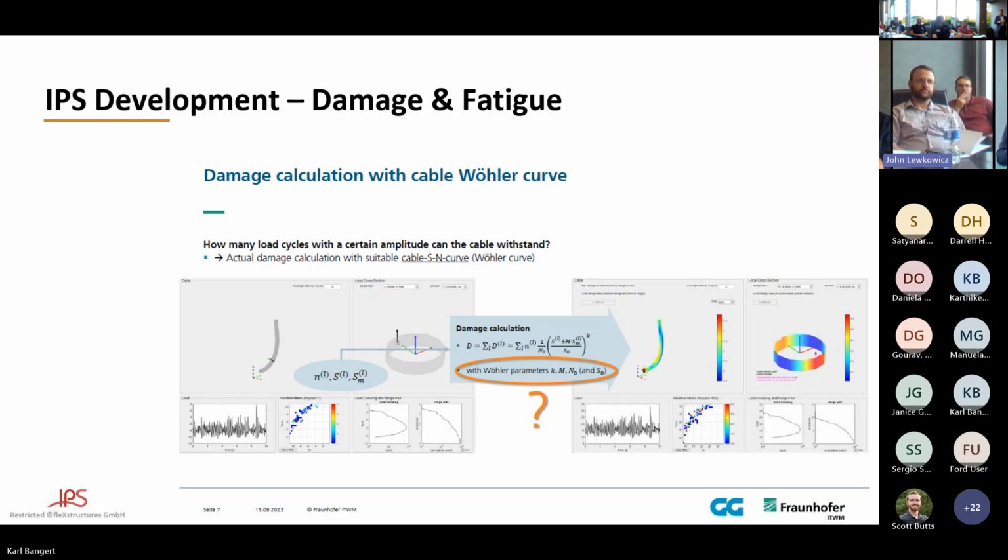Folks at Daimler Trucks, for instance, noticed on their high voltage applications, the relative motion between the high voltage wires going between the battery and the e-motor. You'll get different results depending on whether you're simulating in the standard quasi-static mode, where the weight kind of hangs off of the connectors and you see more of the damage at the connection side, versus what's happening dynamically as the hose flexes and you see more damage along the length of the hose. So we already provide you an indication of where to go with that, with pseudo damage calculations.